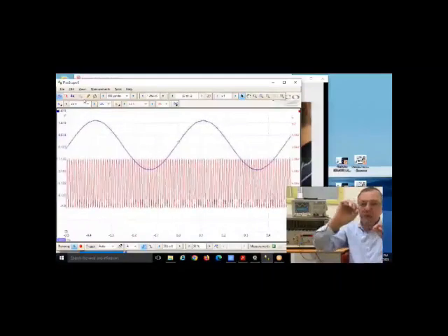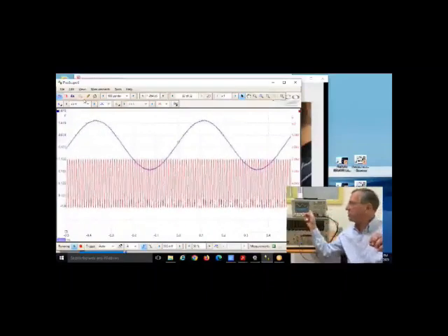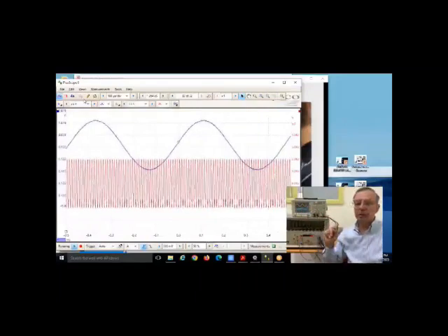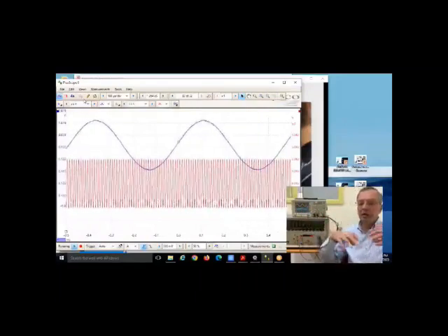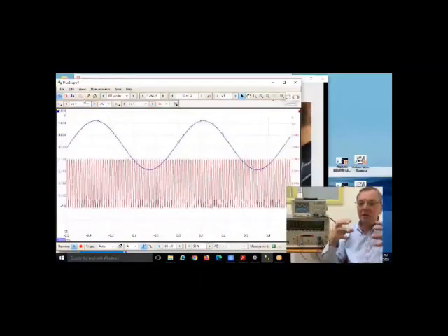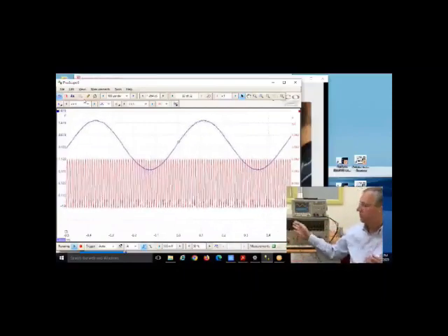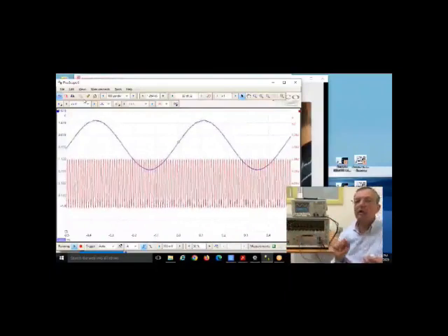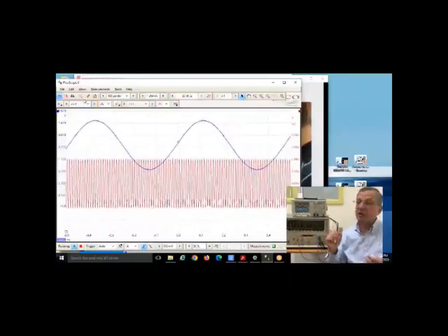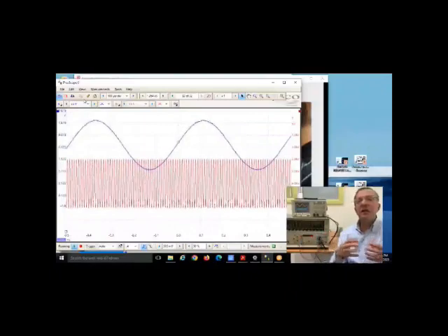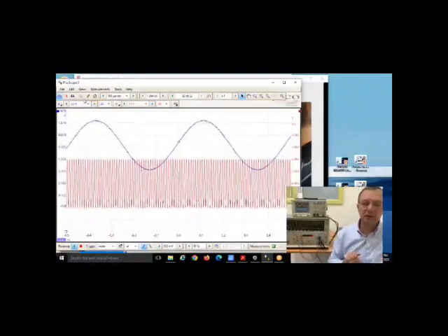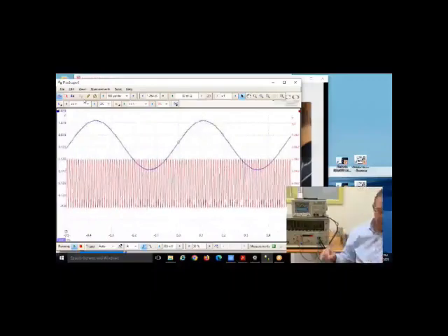What you see in a textbook for an AM waveform is what the student will see on the oscilloscope, either the virtual scope or the real scope. So in the first instance, the students see what they see in textbooks. Then you can develop it further and put in an alternative message, which is not synchronized, and now the student will actually experience what synchronization actually means in telecommunications. So let me jump ahead and show you.